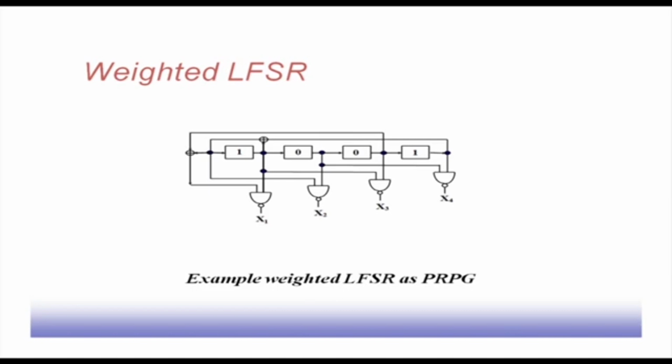So, what is a weighted LFSR? Weighted LFSR is like this. See, this is a normal LFSR, where we have got these cells 1 0 0 1. If you just run it continually, it will generate all the patterns. It is a maximum length one, so it generates all of them.